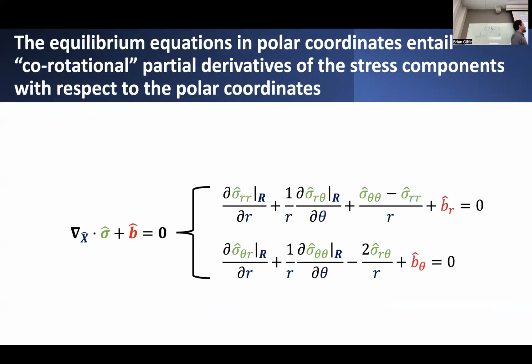The main thing that you should take away from this expression is that we get equations that involve the rr, r theta, and theta theta components of stress. They involve partial derivatives of these components of stress with respect to the two different parametric coordinates, r and theta.